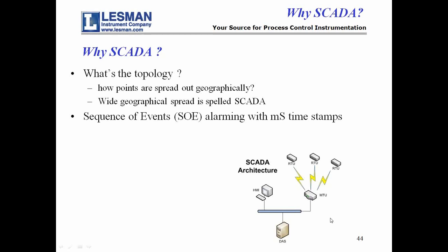Then we get up to DCS control. It's the distributed control system. It's the total integrated control solution package. You do not mix and match an HMI to a controller like you can with a PAC or a PLC. On either of those other ones, if you want to do brand A hardware controller on brand B HMI, that'll typically work. But you don't do that with a DCS.